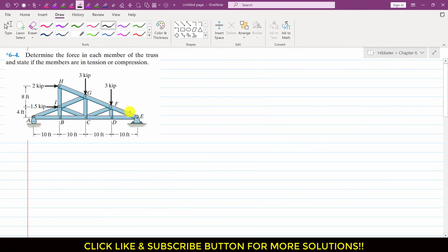First of all, we will start with the supports, so I will find the reaction forces at A. Since here we have the roller support, we will have this force acting upward. Let's say this is AY. And let's say the reaction at E, since it's a pin joint, has two reactions: here we will have EY and here we will have EX.